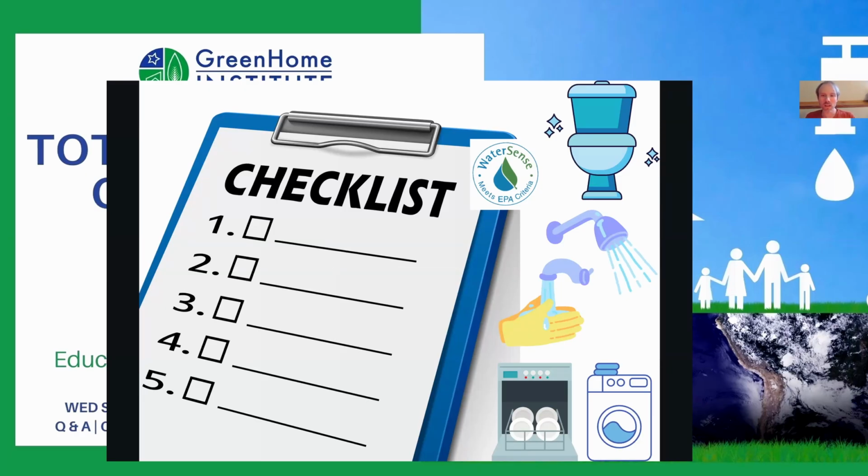So essentially, LEED gets you points for water savings based on baselines, such as at least 1.28 gallon per flush toilets, 1.75 to 2 gallons, depending on the version of LEED, per minute on the shower head, and then 1.5 gallon per minute on the bathroom aerators, but not looking at the kitchen aerators in the prescriptive, but we'll get into those.